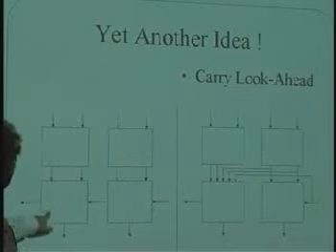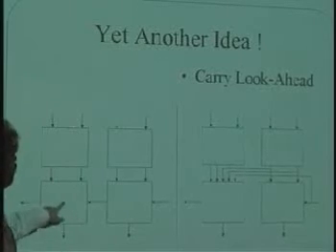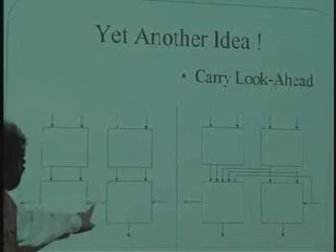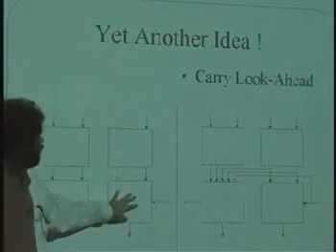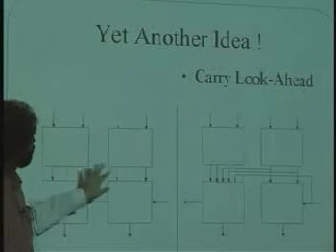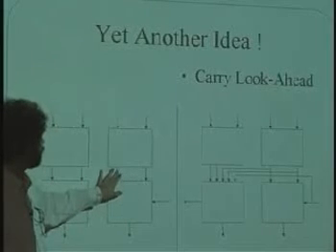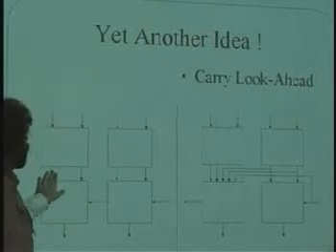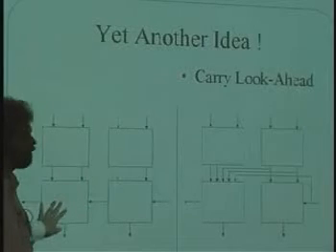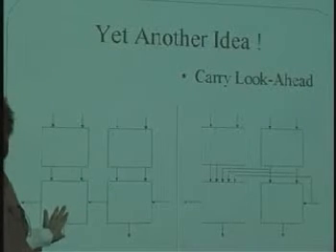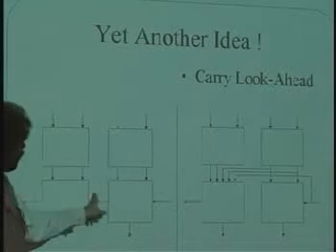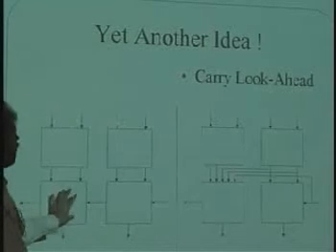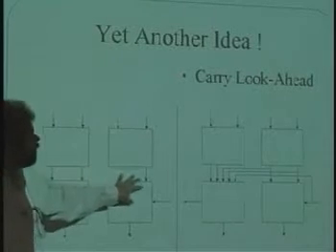But I can actually design some parallel logic here, and I can break this chain, and I can look ahead of the logic down here and say, in certain cases, when this thing generates and this thing propagates, and this thing generates or this thing propagates, I can actually figure out what function I should use in order to create the sum and the carry out of this stage, and I thus break this link here by looking ahead for what the carry might be.